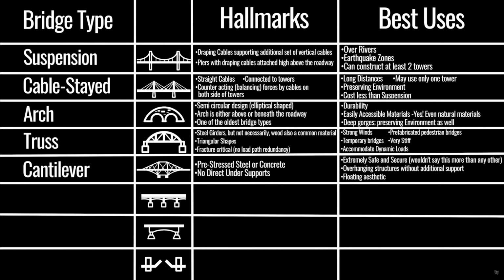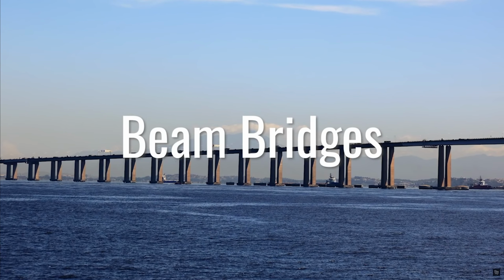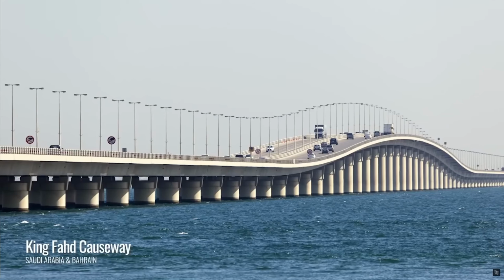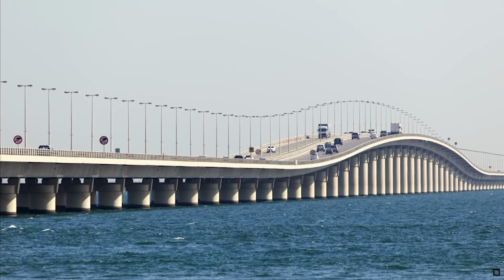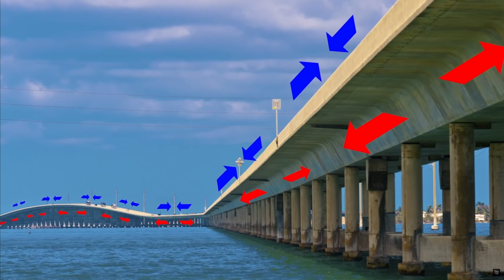What other bridge types are there? When we're talking about plank bridges, those planks are acting as beams. And so they have to resist what we call bending moment. A bending moment is what causes these beams, in this case, to experience both tension and compression. Compression is at the top as it begins to bend, and tension is at the bottom as it begins to deflect.